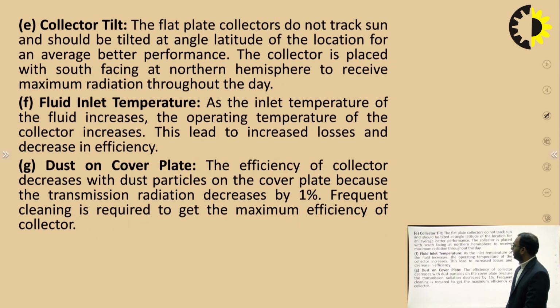Then the other parameter is collector tilt. The flat plate collector does not track the sun and should be tilted at an angle equal to the latitude of the location for better average performance. The collector is placed facing south in the northern hemisphere to receive maximum radiation